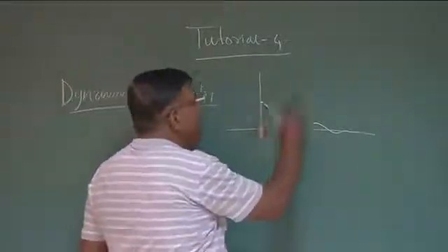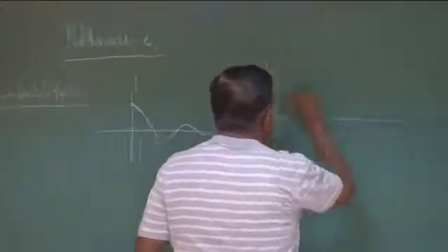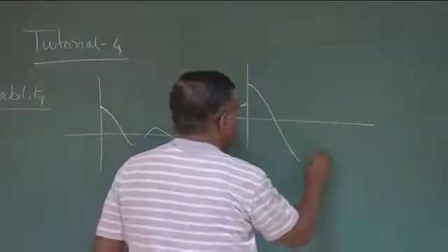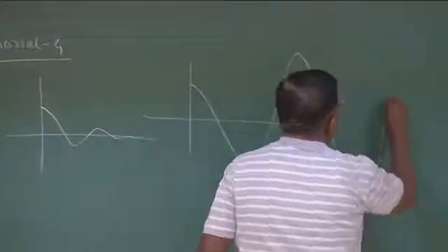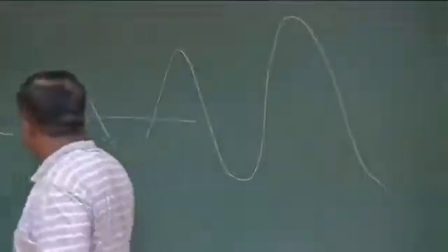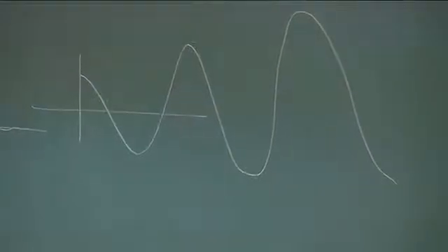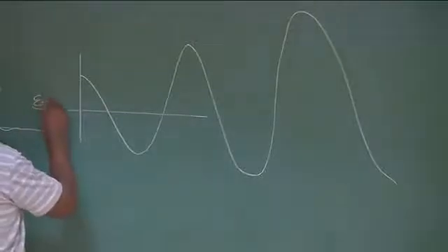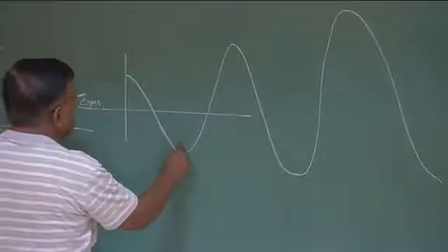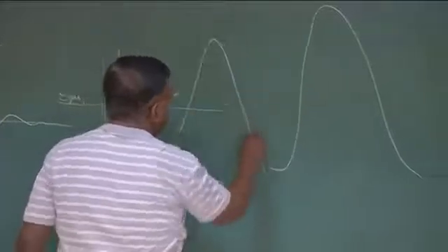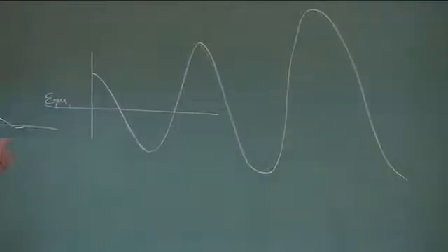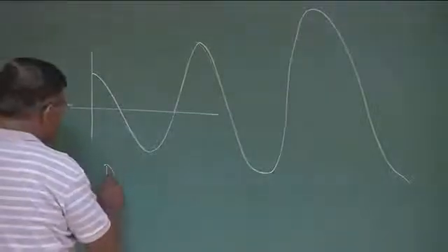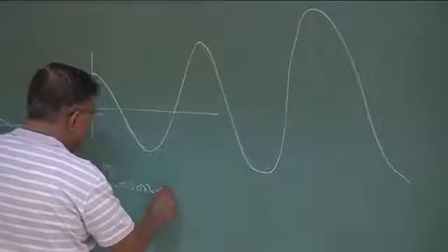It's possible it has the initial tendency to come back, but every time it is going further up and up like this. So you could see it has an initial tendency as soon as it crosses the equilibrium. Say this is the equilibrium, it goes, again it tries to come back to equilibrium, again overshoots, and the amplitude goes on increasing. So this is a typical case of dynamic instability, and typically this is a phenomenon close to resonance, right?